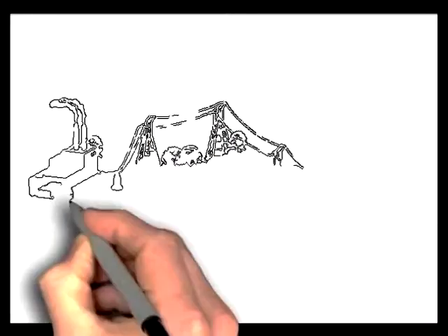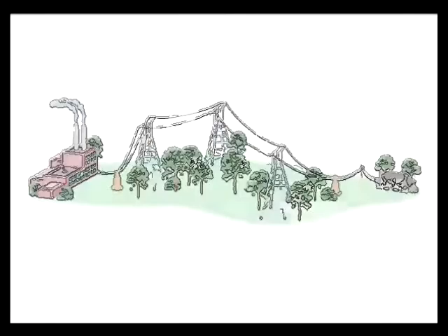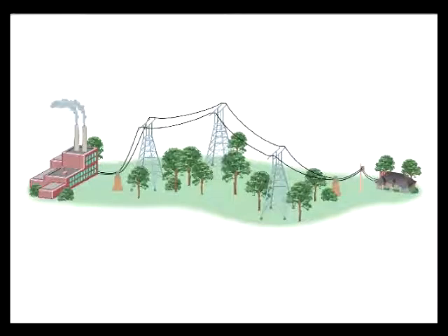Transformers play an important role in the transmission of power between electrical generating plants and the communities they serve. Whenever electricity is transmitted, there is always some loss of power in the transmission lines themselves due to resistive heating. Since the resistance of the wires is proportional to their length, the longer the wires, the greater is the power loss. The resistance of the wires is also inversely proportional to their cross-sectional area, so thicker wires are used to help minimize the power loss.